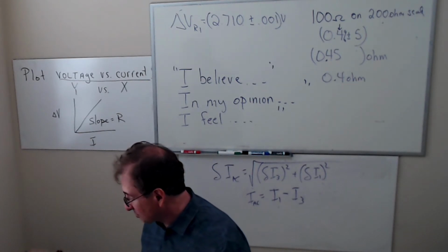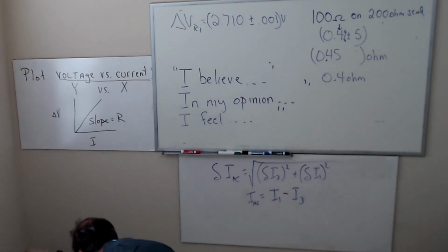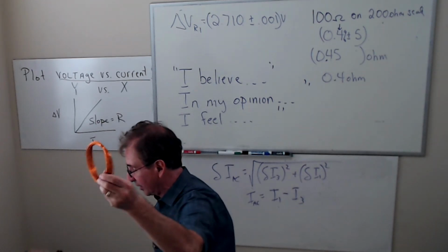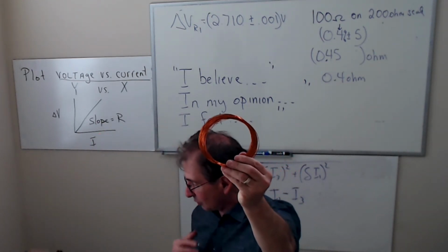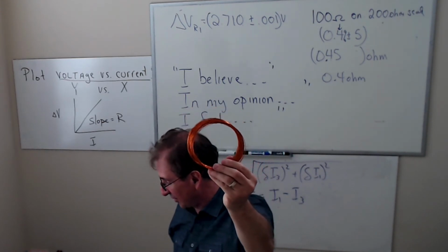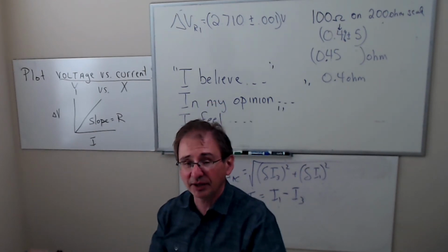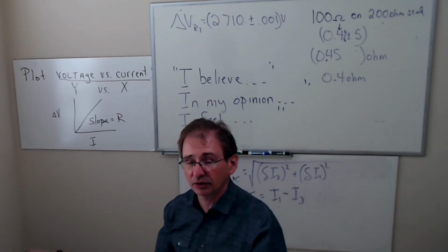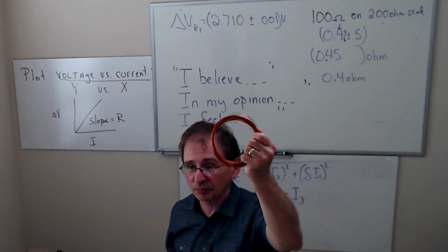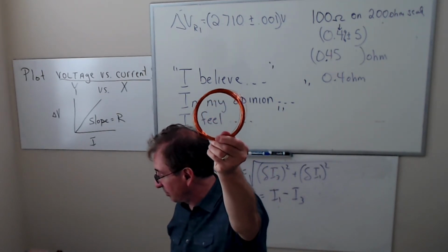Yeah, this is magnet wire. It's copper wire, and it has an enamel coating on it. The reason you want the enamel coating is that it makes the wire thinner. So when you wrap it, you don't get a thick wrapping, because an insulator coating usually is quite thick. This makes it real thin, and it makes it easy to bend.